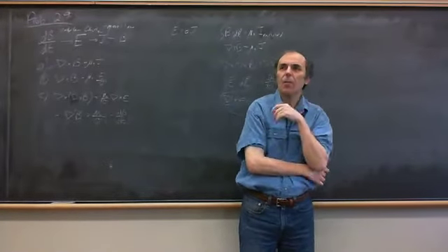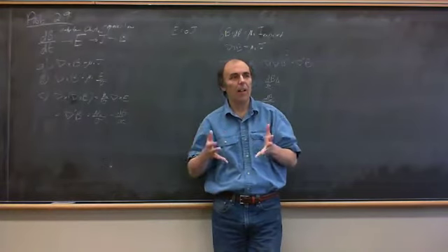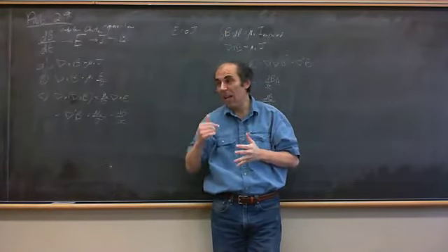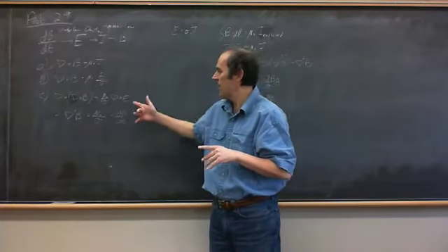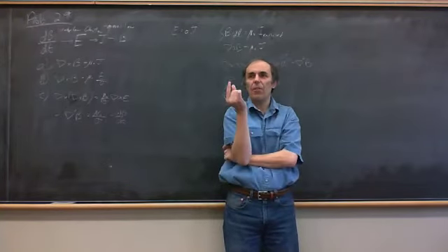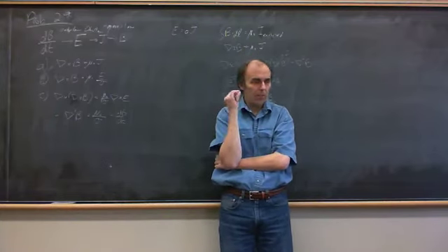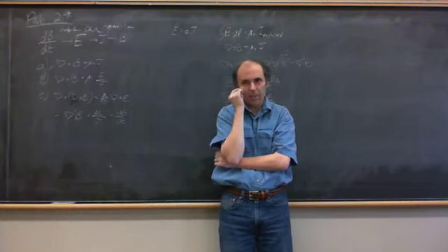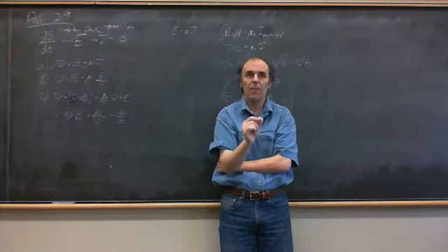And they're using frequencies that are up around 10, even 100 gigahertz electromagnetic fields. If you go up to that high of a frequency, you can calculate the skin depth, and the skin depth is only a few millimeters, which means these fields don't penetrate into your brain or into your body very far. They really penetrate about the thickness of the skin, so skin depth's not a bad term for that.